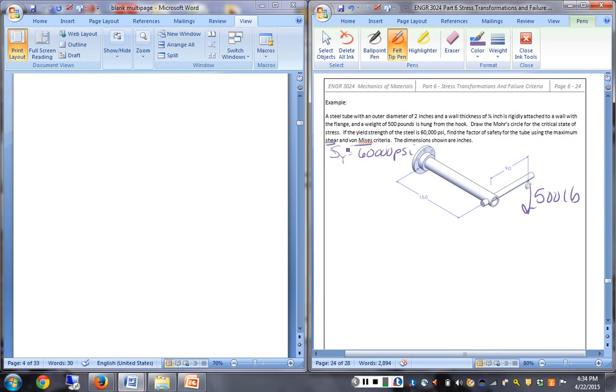All right, so what's going on? What kind of stresses are we going to get from this loading scenario? We got torsion going on for sure. We've got normal stress from the bending, and there is also the shear. Now, again, the caveat is usually that shear is negligible if that shear value is small compared to the resultant moments, and we'll do the math to make sure.